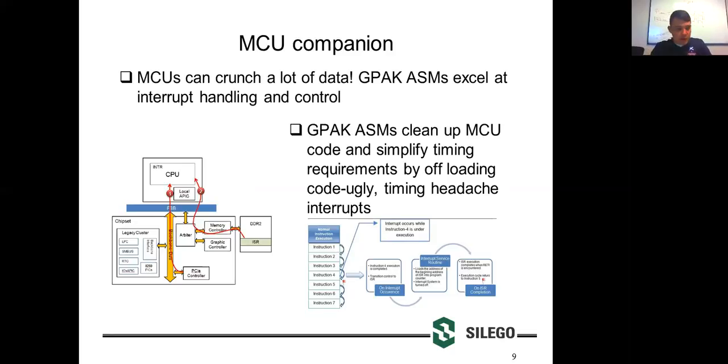It was very common when I was working in the microcontroller world to see that the actual code that drove the device was 10% of the code, and 90% of the code had to do with failure modes. What happened when something didn't work right? What happens if the user came along and yanked out the battery charging cord in the middle of the battery charge? What happens if you ran out of memory and the stack started overflowing? And what happens if the motor's running and the temperature sensor goes off? How fast do you need to respond to shut that motor down before everything overheats and melts down? And what's the timing associated with that? And most of these problems are all related to interrupts.